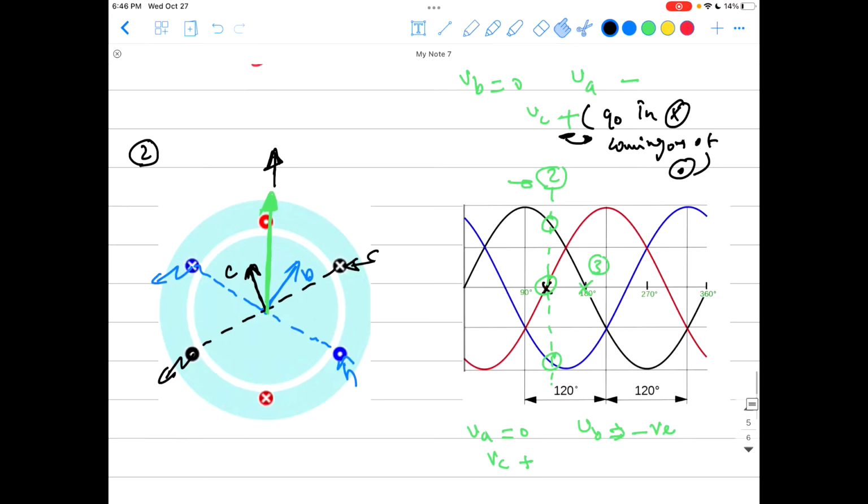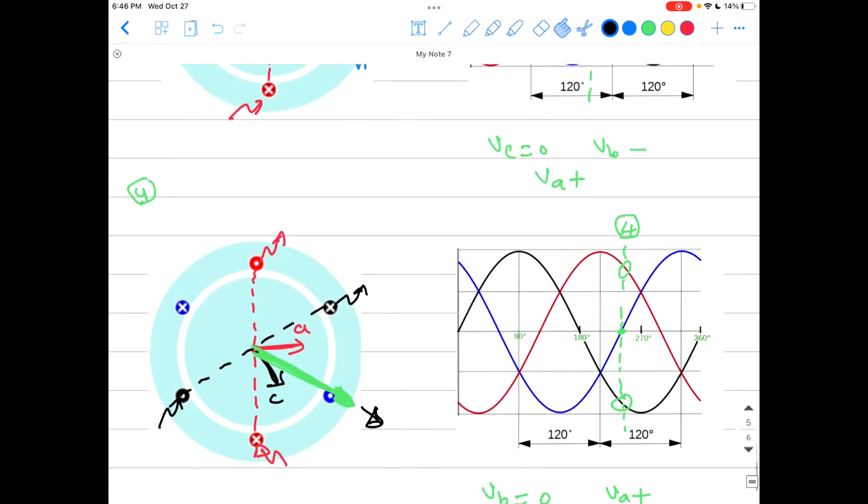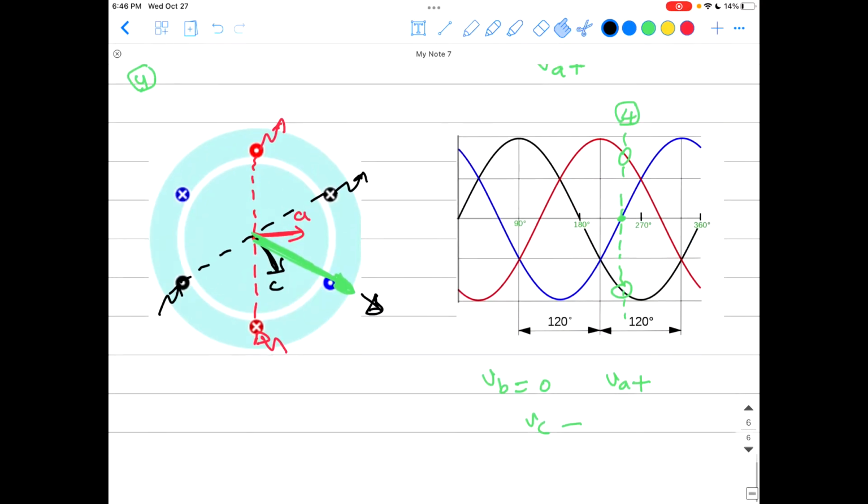So this is just rotating around the circumference of the machine. So here is the magic of this. From 3 different phases, if each one of them was fed from a different supply, each and every one of them would look like a pulsating magnetic field that is fixed in position and keeps changing magnitude. That we call the pulsating magnetic field. And it's not useful anyway, okay?